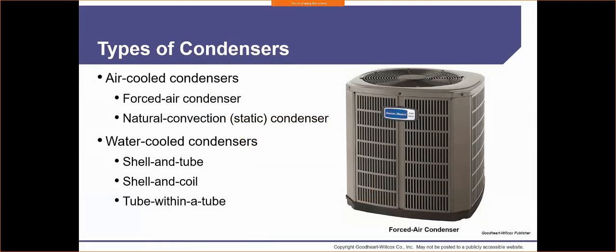And so we've got a picture here of a traditional condensing system, or outdoor condensing system. All right, we've got air that travels through the grates on the sides, and then it comes upwards, all right? And as that air comes upwards, it absorbs the heat that was trapped in all these little tubes that are inside here, and then it expels the heat upwards. So we don't want to put anything on top of our units when they're running, all right? The reason being, all of our heat transfer is happening through the top where the condenser fan motor spins. So that's critical to understand.